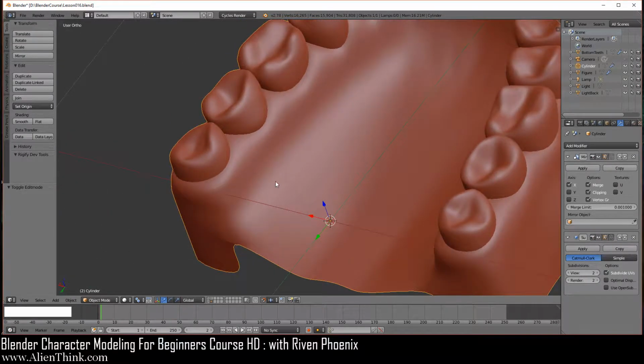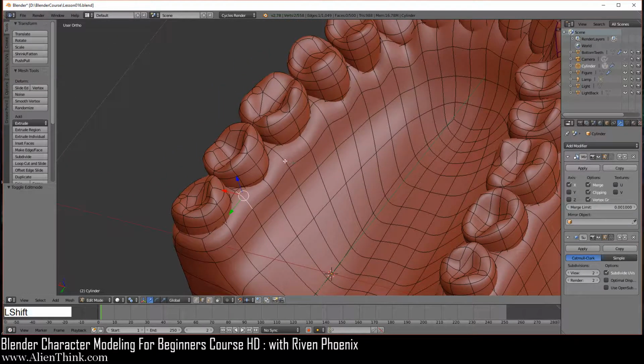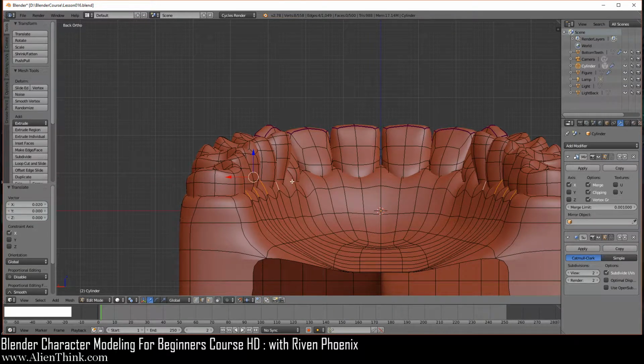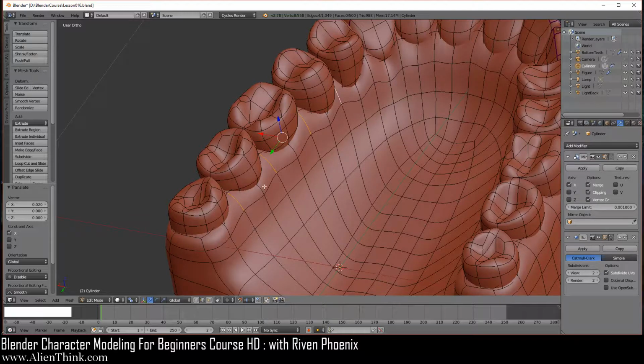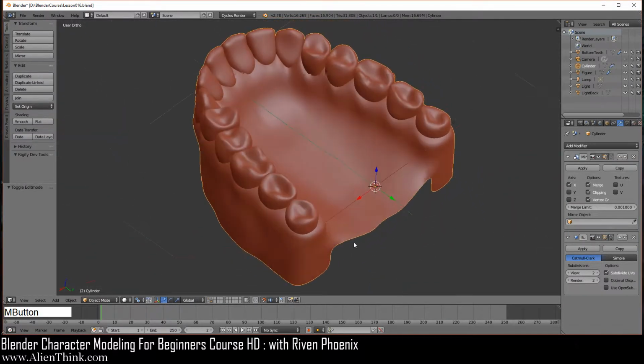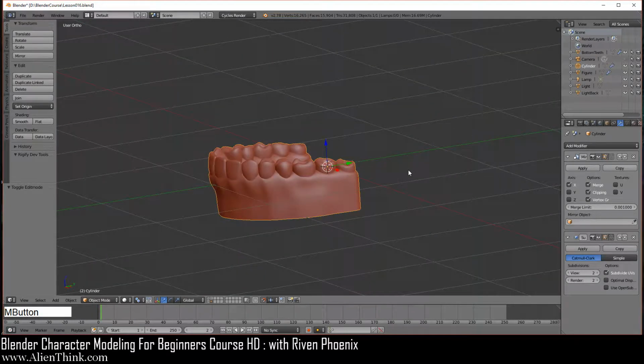That's all we're doing. Just press Tab, then click on this one, and then hold Shift and click this one, and this one over here. Press Control 1 to go to the back view and take it to the left 1, 2 times over here to bring it in a little bit. Then you can click on this, hold Shift and click this one, this one, this one, and this one. Press Control 1 again and just bring it out 1, 2 times over here. If you press Tab, you can see how we get these little nudges over here. So that solves this issue over here.